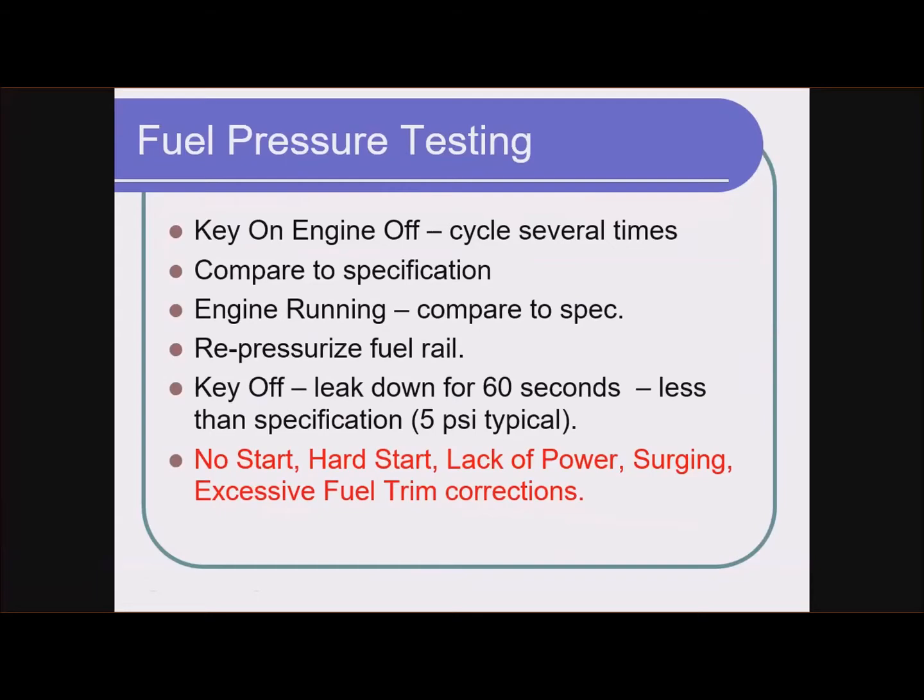So right now we're just talking about port fuel injection. We're talking 50, 60 psi, not super dangerous. Obviously, fuel is very flammable, so if you're working around a hot engine, you need to be cautious not to spill fuel all over a hot exhaust manifold and start your car on fire. So now we've done a regular fuel pressure test, key on, engine off, engine running. We like the readings we've gotten. What do we do next?